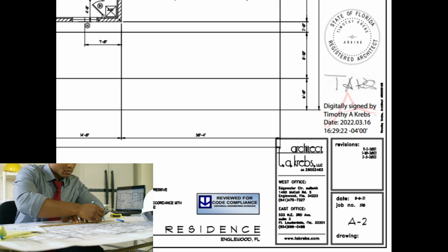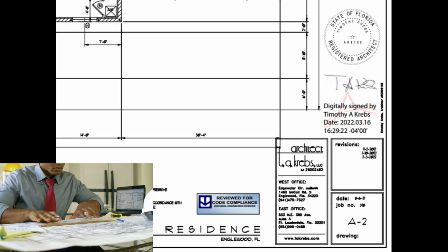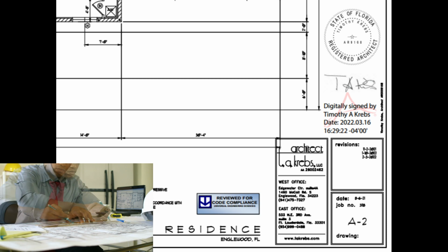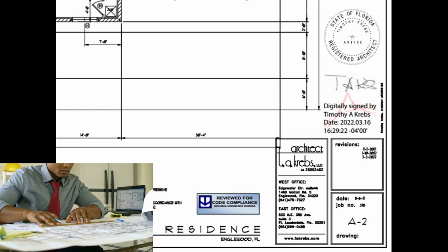On the lower right corner are the following information: project name, project address, name of architect of record, plans date, and page number. Architectural sheets also show floor plans like a bird's eye view of the building. They may have details like dimensions, wall layout, cabinet placement, door and window placement. Different walls usually have different wall hatch patterns.